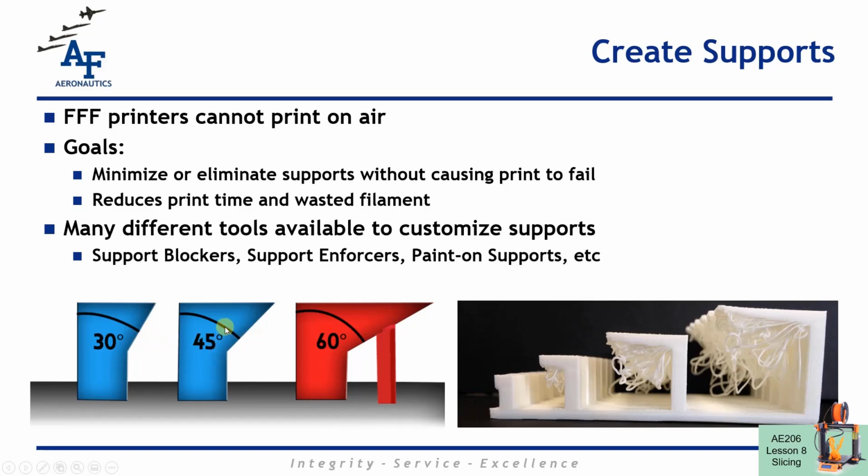And that's even true if we have an overhang at like 45 degrees. The print head is going to be extending the next layer out a little bit further than the previous layer, but it's still supported a little bit by the previous layer. When we start getting to overhangs of 60 degrees or 70 degrees and higher, you really can run into issues where the next layer up is not being supported well enough by the previous layer. And that's where we need to add supports.